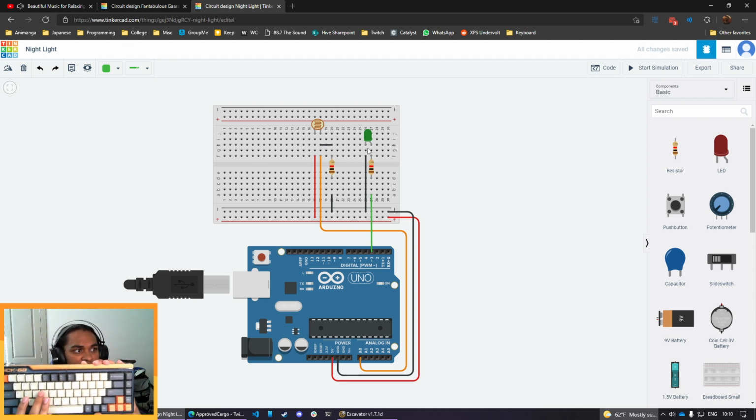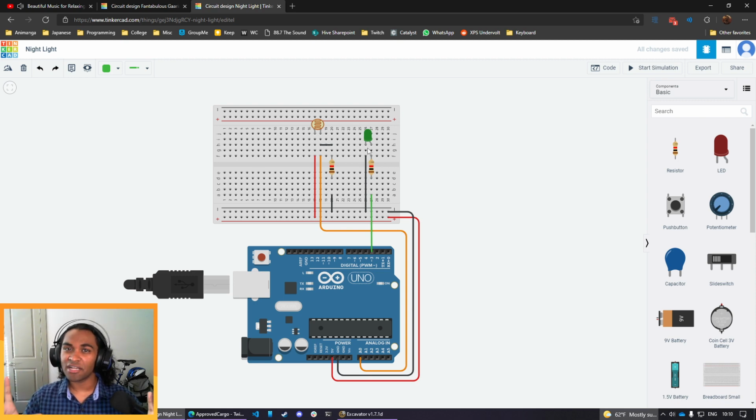Every time I click one of these buttons, there's a microcontroller inside my keyboard that keeps track of which button I just pressed. With the keyboard, it's a bunch of rows and a bunch of columns of wires, so it creates a kind of grid system. The keyboard sees which row is selected and which column is selected, and it can bring it right down to that single key.